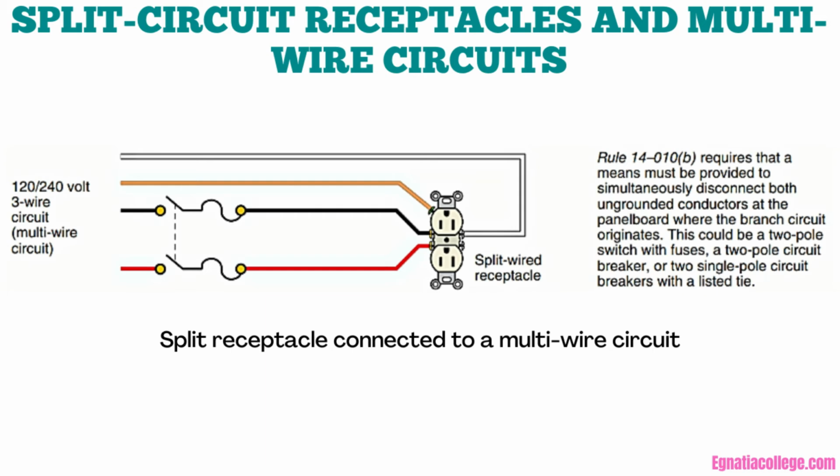The local inspection authority may permit you to make connections of the neutral at the terminals of the receptacle when looping between the counter receptacles in the kitchen.